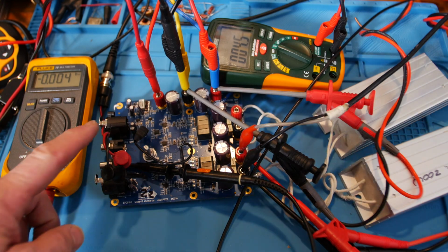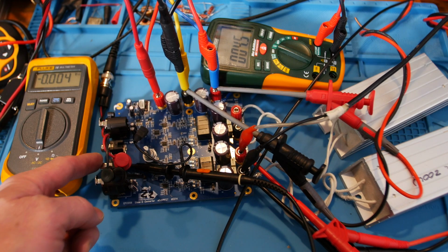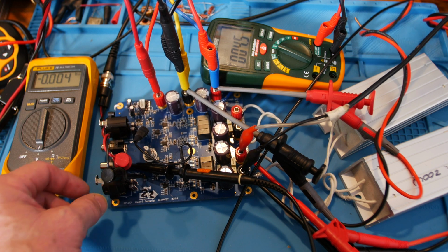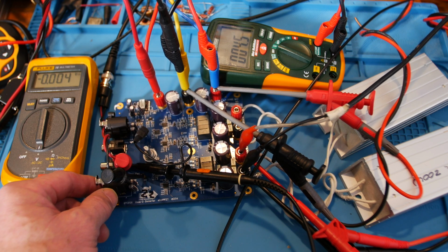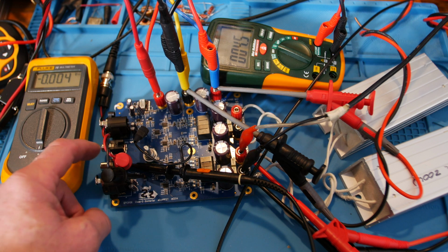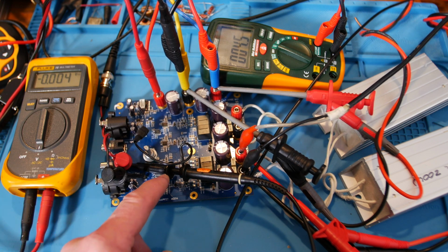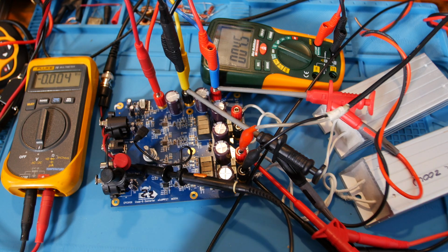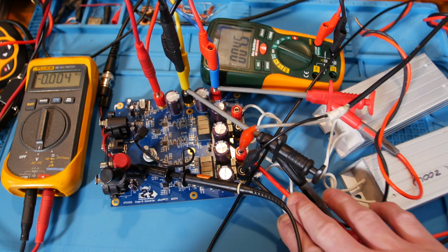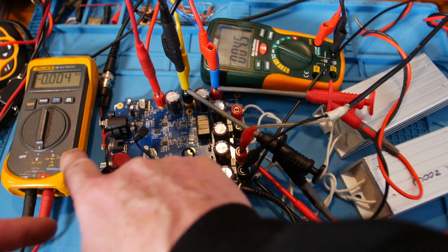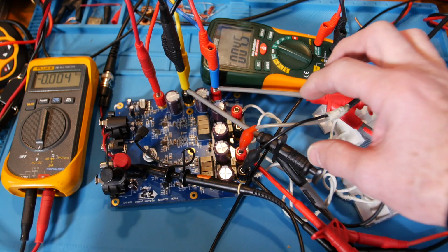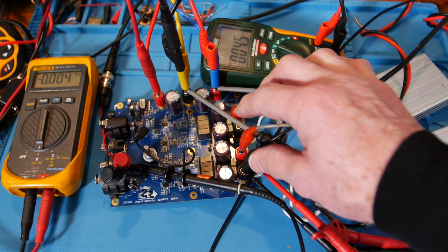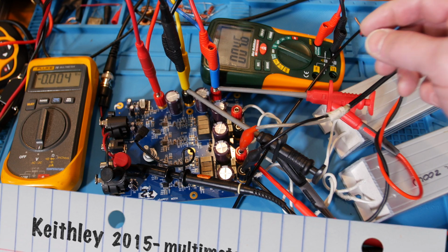And we have our signal coming in here into the RCA connector. Maybe I should come in through the XLR connector for the balanced input, which I haven't done yet. Okay, so I'm coming through the XLR. I've got the oscilloscope probe looking at the input signal, and over here I have a differential probe looking at the output signal. We're just coming through this right channel right here, and this probe right here is a THD meter. It's the Keithley 2015 THD multimeter.